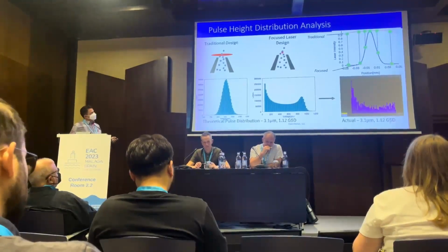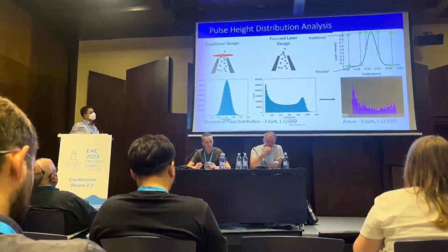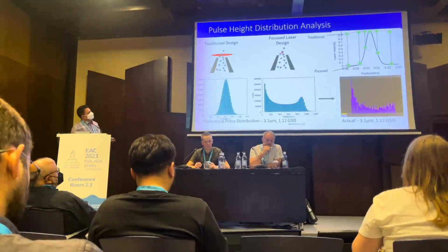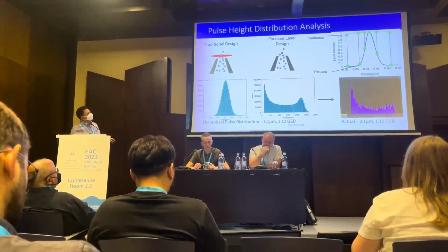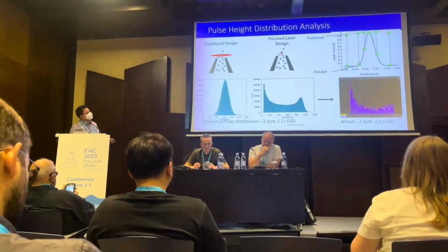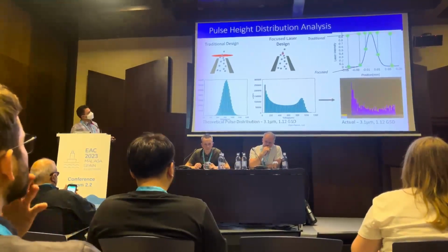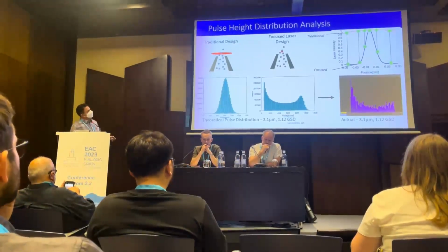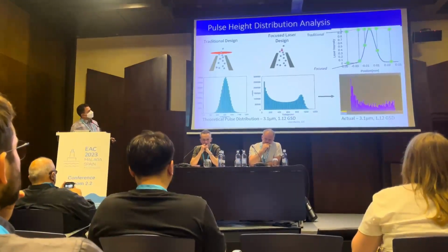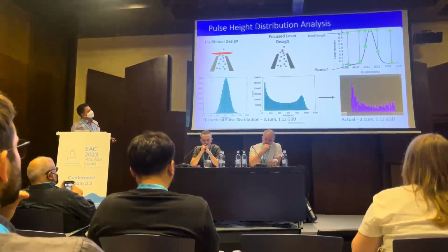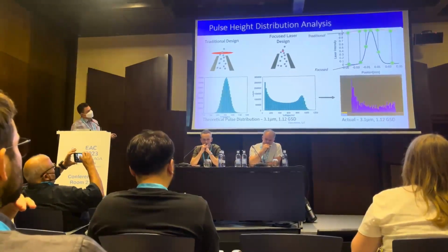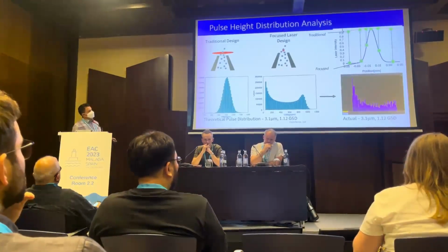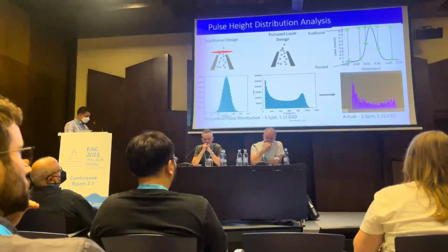The reason is that the beam is obviously smaller than the nozzle, so there's going to be a lot of particles that have 0 signal because they never traverse the beam. Here's a good example of that. The orange line is a traditional laser intensity across this; pretend this is the nozzle from negative 0.3 to 0.5. That's a traditional laser beam intensity profile, and here is our laser beam intensity profile, this sharp curve. You can see a particle traversing here gets no signal, whereas if you go through the traditional beam, then you get some signal. So this distribution is due to that mechanism, and we see that in the real world.